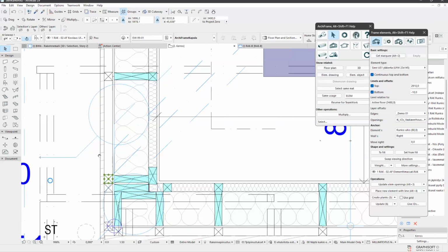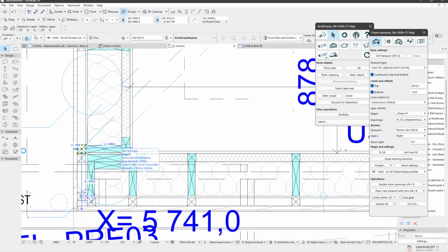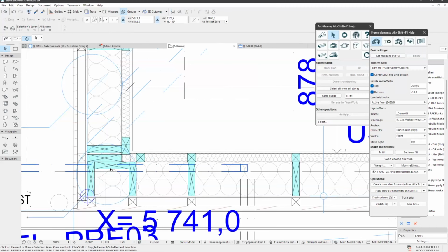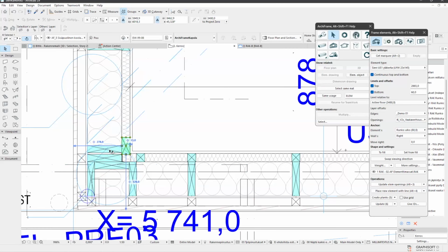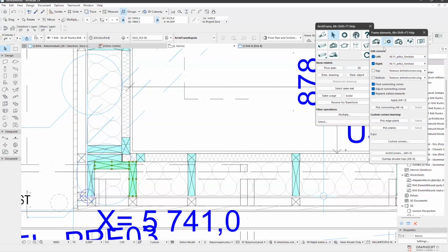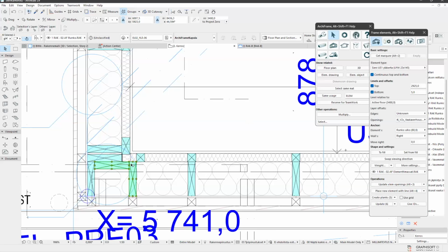Yeah. And then one strong point of ArchiFrame is the flexibility. So you can edit whatever the automation does. You can work the ArchiCAD way, so you can drag these things around. You can delete those and edit as needed. One note about this, the corner. So this part was generated by corner rule, and for the connecting wall, this part, they are taught to ArchiFrame that when we have this type of corner defined here, we want to have these two pieces like this.